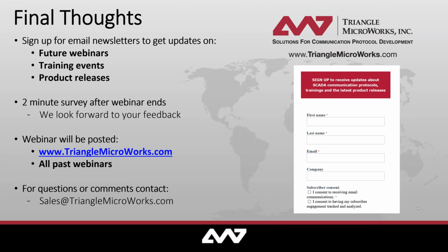So, in a broad sense, if you can imagine the slide where I had a layout of a substation, and I talked about primary equipment and secondary equipment. Those pieces of secondary equipment are going to be servers typically, right? So they're going to either interface directly with pieces of primary equipment, our breakers and things like that, or CTs and VTs. Or in some cases, it might just interface with other pieces of secondary equipment, right? I might have a protective relay that is getting its sample value stream from one IED and interfacing with a second IED in order to trip the breaker. That's still going to be a server.